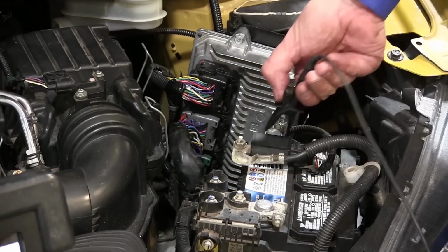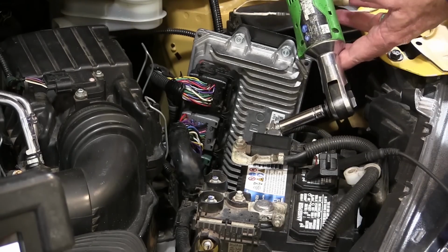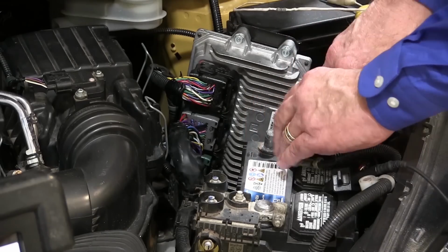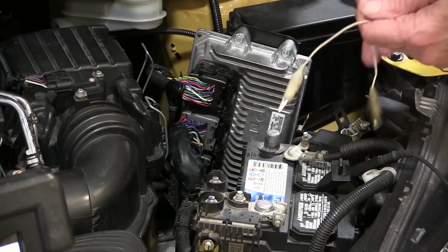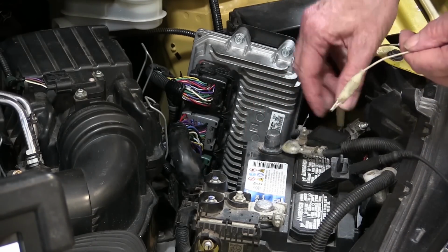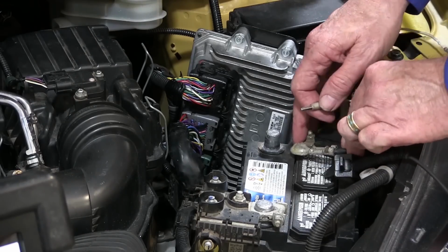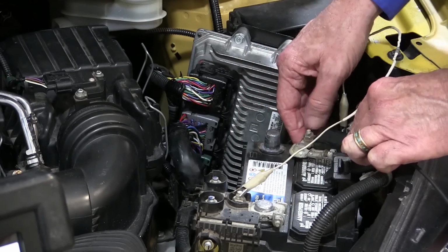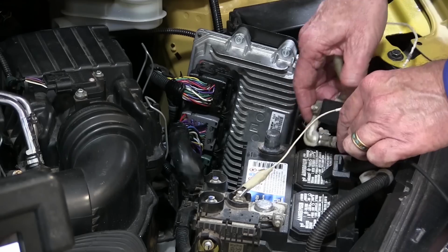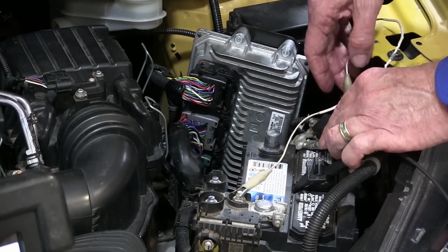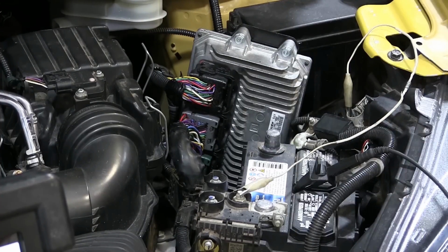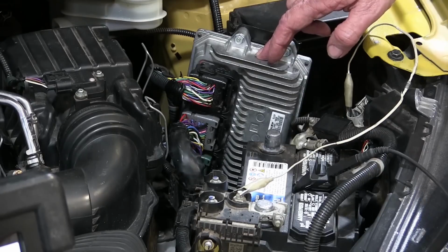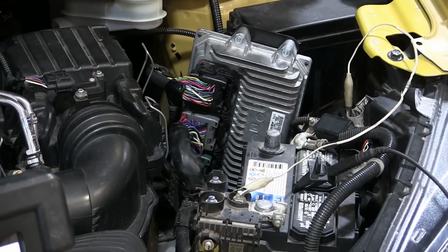Okay, what I want to do is take the negative cable off the post of the battery. Pull that back over here. I have a 10 ohm resistor in this drain wire, and I want to just connect it across. Now what I want to do is let that sit for about 10 minutes. I want to drain the computers. Mainly what I'm trying to do is reset the gates on the PCM here. So let's just let that sit and then let's see what we get.